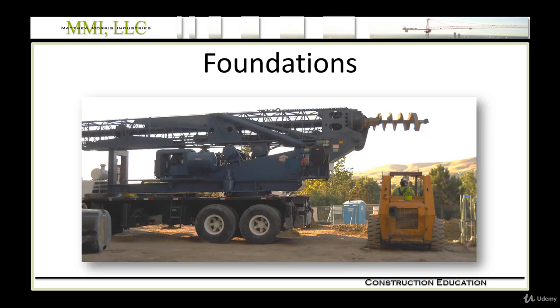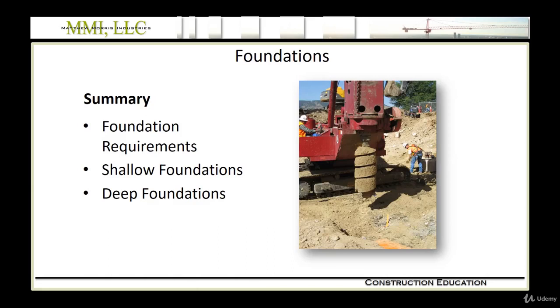So the responsible parties here, of course, we've talked about the geotechnical engineer quite a bit. They determine what soils are present and predict the behavior of those soils. But the structural engineer takes it from there, and they design the foundations based on that criteria. This scope falls under Division 31 primarily, which is earthwork, but portions of this scope could be in Division 3, for example, under concrete. So in this class, we'll talk about the different foundation requirements. What exactly does the foundation need to do for us? And we'll talk about the two different types of foundations. They fall broadly into shallow and deep foundations.